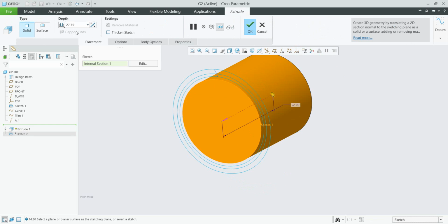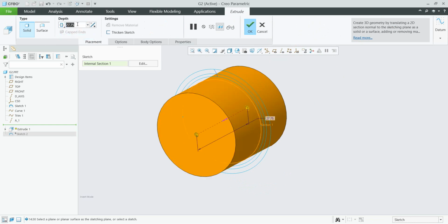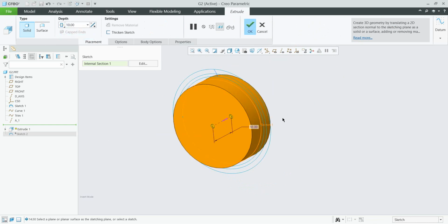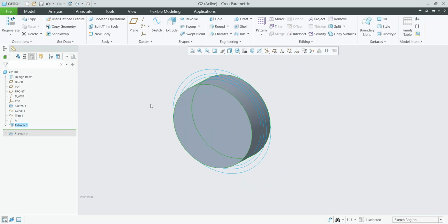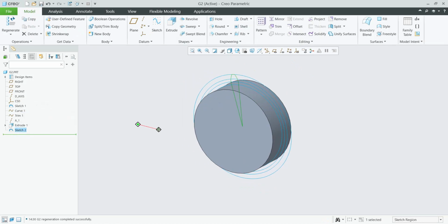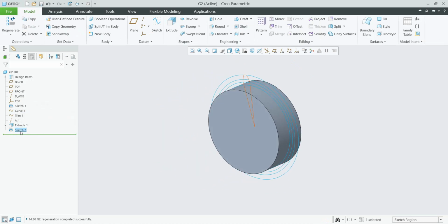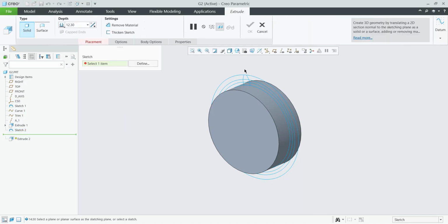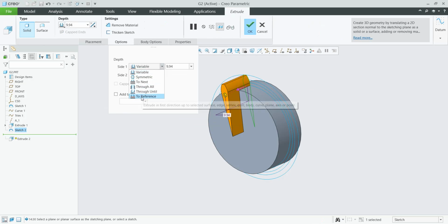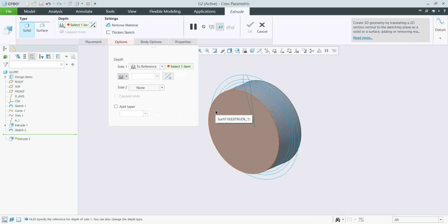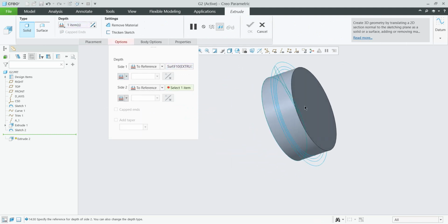And when we extrude, we can use symmetric, and for example, thickness will be 10. It's about the specification, what you would like to use, confirm OK, and now we can drag and the sketch will be created. So what does it mean? Now we would like to select this sketch, and we would like to extrude the latest sketch. And again, maybe we would like to specify the thickness, but also you are able to specify that you would like to have the reference on the left side, and also maybe you would like to specify the reference on the right side.